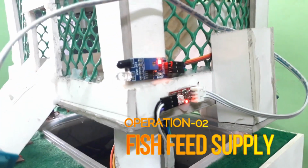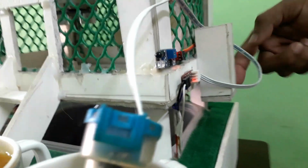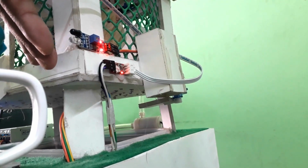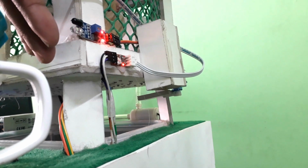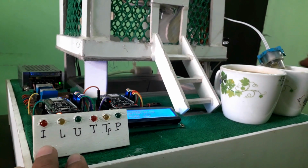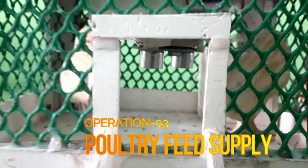Next, we will make sure of proper feeding for our fish by using an IR sensor. We use a servo motor to make sure of proper distribution of feed for the fish. When we place an obstacle in front of the IR sensor, at that moment the servo motor will provide feed to our fish. And you can see that when the IR sensor detects any obstacle, this indicator will be turned on.